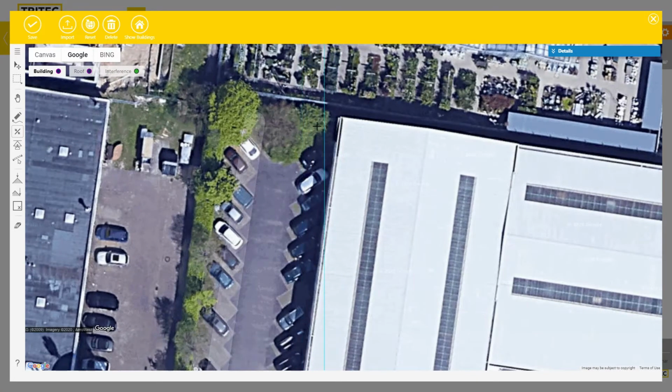The first click, it's following my mouse pointer, as you see. And the first click is setting the rotation point. And the rotation point should be set somewhere next to the end of the roof area. So I'm just clicking with my left mouse button, and you see now this is fixed. I have the turning point, and the nearer I am to the turning point, the harder it is to do the setting.